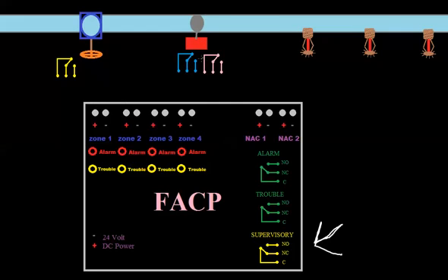First, you'd have to go to the water flow switch, and I'll explain why. Let's start with zone 1. We didn't program it for supervisory, as our panel doesn't have that capability. Let's go positive and negative to common normally open on the water flow. So when water starts flowing, it's going to push this paddle and change the states of these two. There's two sets of contacts. There's usually two sets on the tampers as well, but we don't use those. On the water flow, we are going to use those, and I'll show you how in a minute.